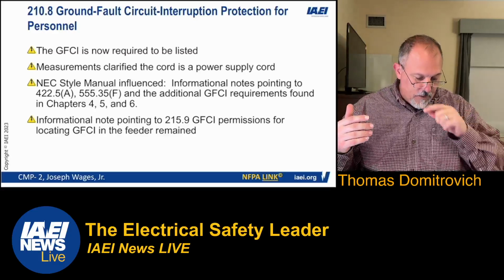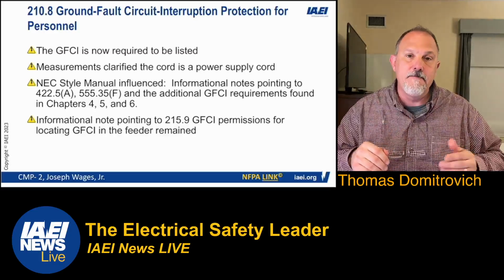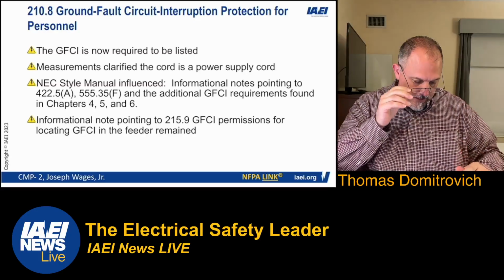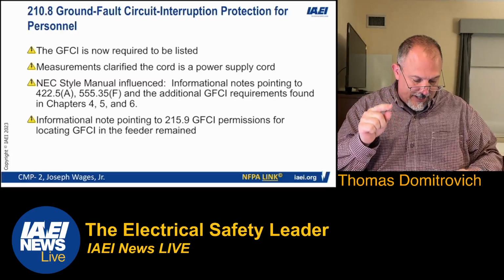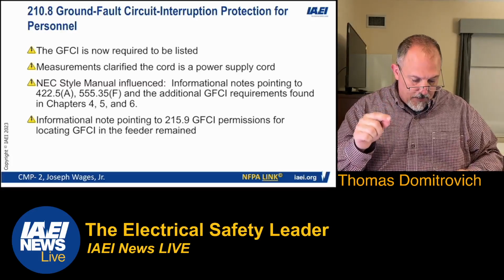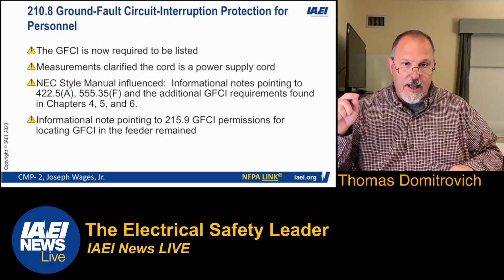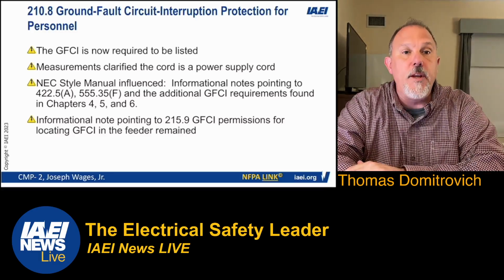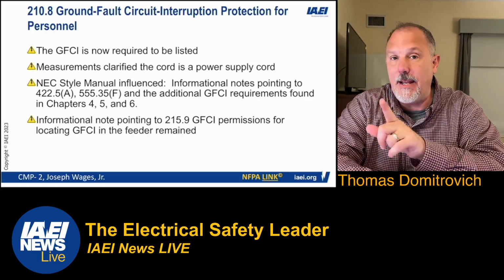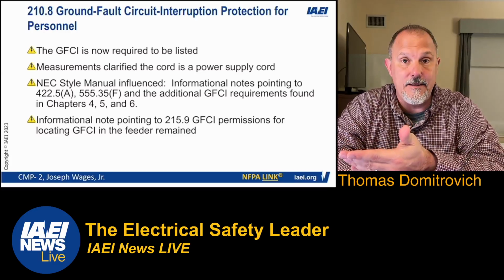First of all, we changed the parent text in 210.8. We have modified language that says a listed Class A GFCI shall provide protection in accordance with 210.8(A) through (F). That first sentence, we did a couple things. We recognized in the 210.8 parent text that a GFCI needs to be listed.